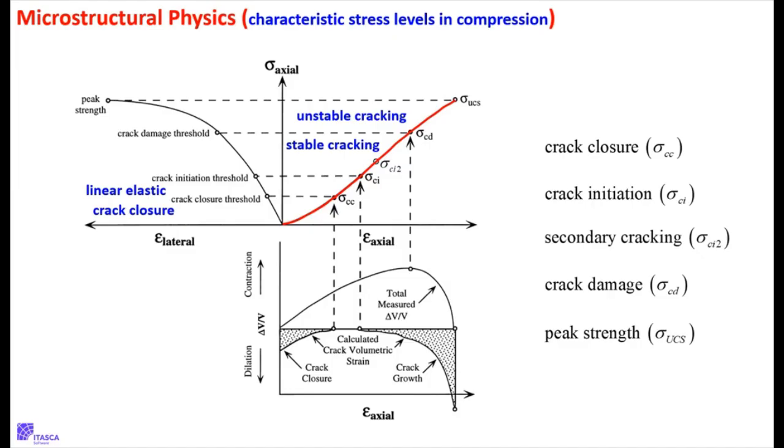So this is a quasi-static test, and what do they measure? Let's talk about what you measure here. The simple thing you measure is axial stress against axial strain. So this is the curve you get, okay? And I'm only drawing it out to this point. We'll talk about this in a minute, but what else do you measure?